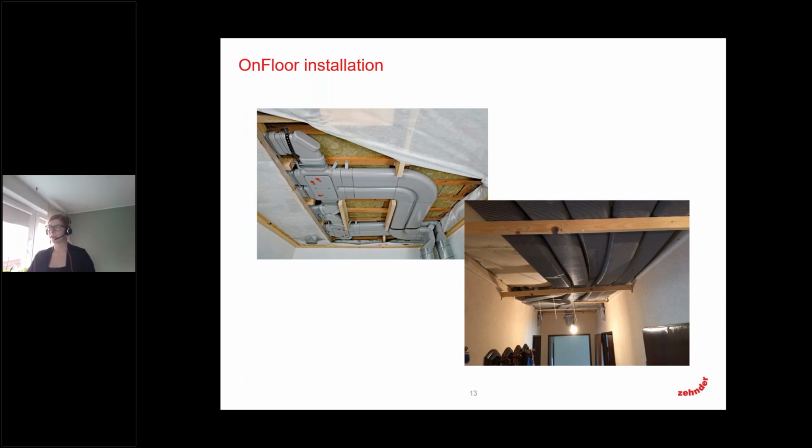So here, if we need to consider that we have many different rooms where the supply air can be, then we would have one main duct. We would need a silencer between all the different rooms to make sure that the noise from one room will not be carried to another one.